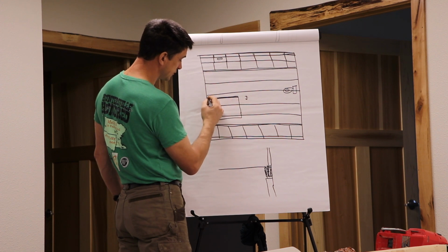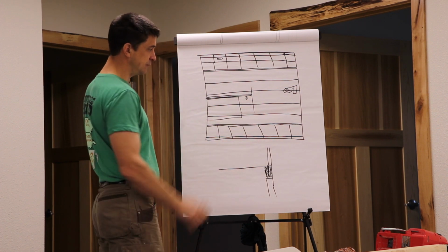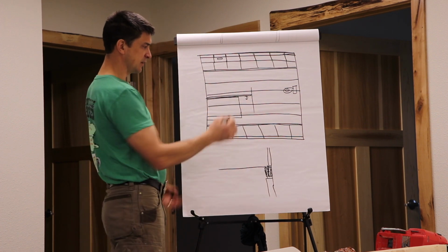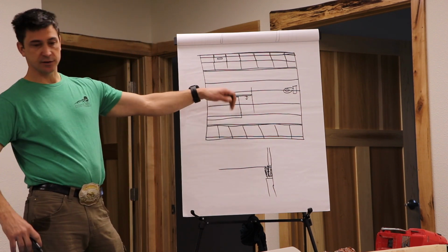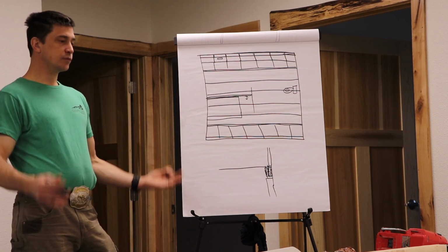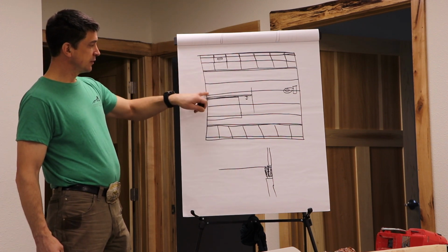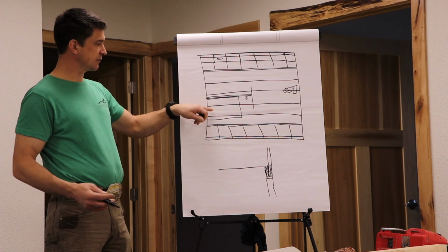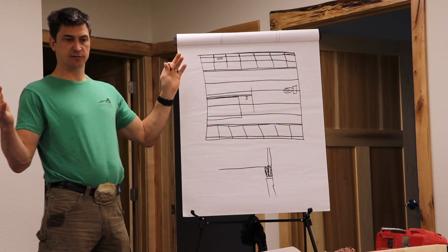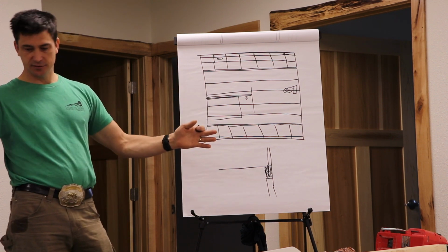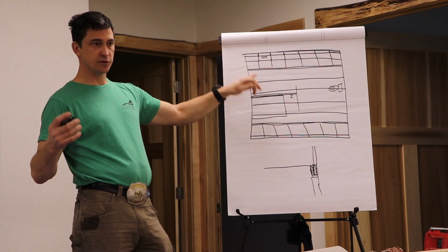We've got one on the plan that's showing a double here over to the beam. So we've got a double there, and this one's 3 inches away. Just move it over, put your double. You don't need to have this one 3 inches away. Nobody really needs that. And you can measure, and you're like, oh, it's 14 feet. It doesn't matter. We're 15'6" to the edge of this opening. So our sheathing is going to come out at 12 feet and 16 feet. So it's not going to land on this one. So there's no reason to put it in.